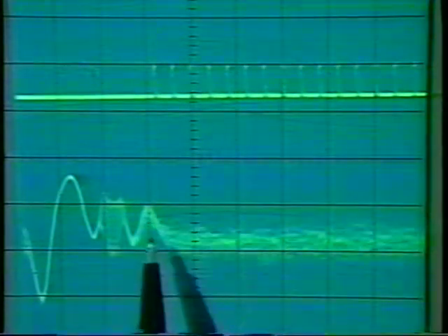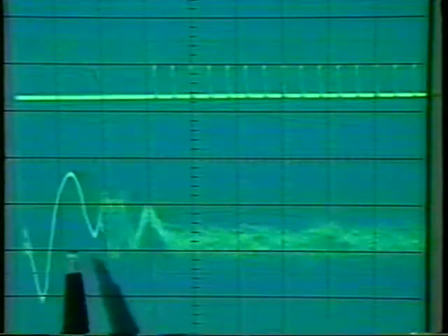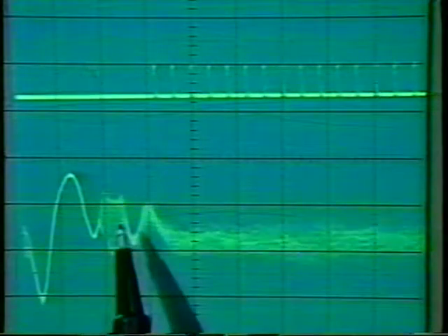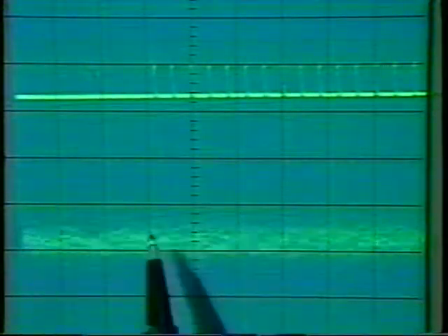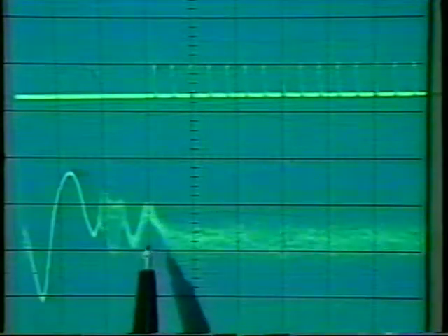We cannot sample the atmospheric echo any lower than here because you are in the transmitter recovery here. There's no atmospheric echo contained in this. The only atmospheric echoes are out in this area here. So you're restricted to your minimum range, which is right here.